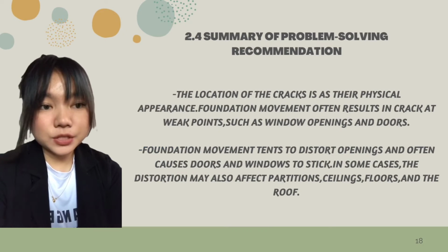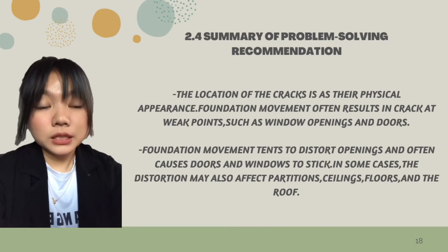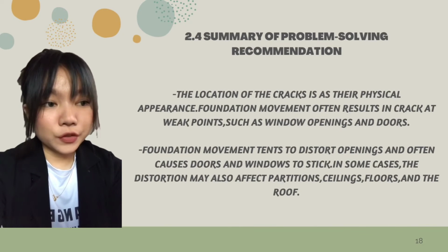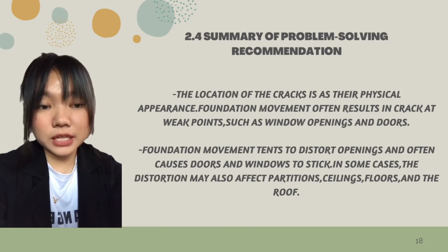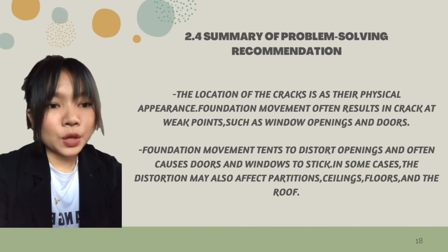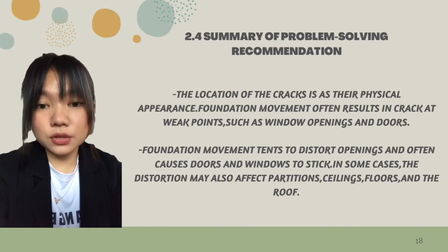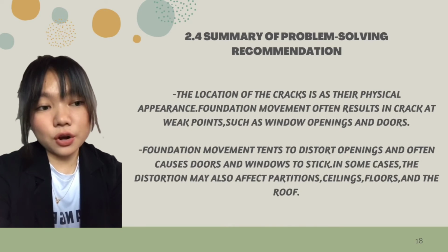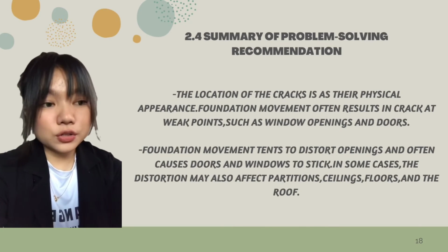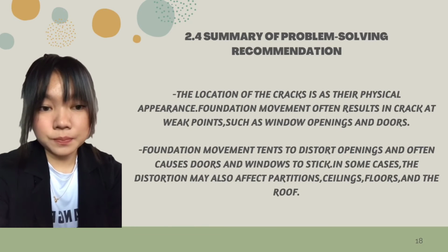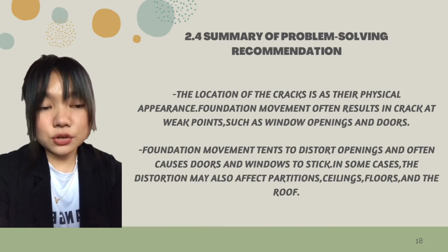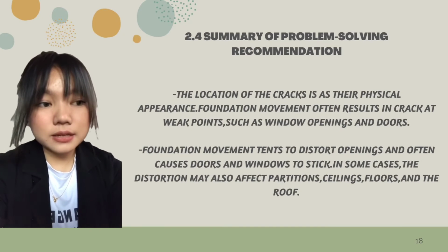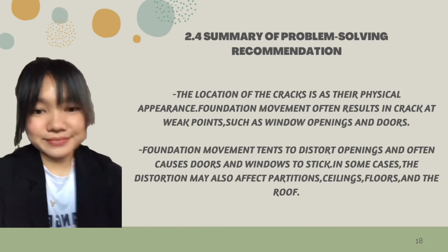Summary of problem-solving recommendations. The location of the crack is as per its physical appearance. Foundation movement often results in cracks at weak points, such as window openings and doors. Secondly, foundation movement tends to distort openings and often causes doors and windows to stick. In some cases, the distortions may also affect partitions, ceiling, floor, and the roof.